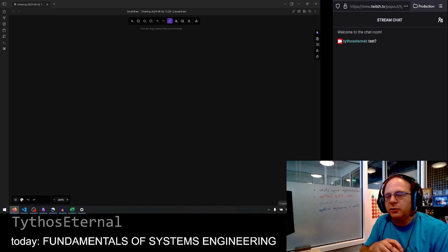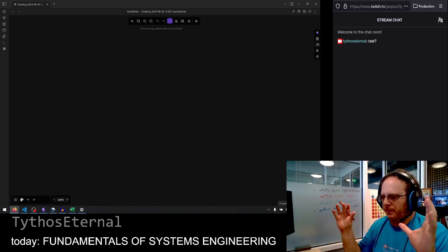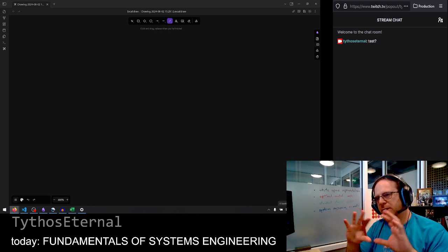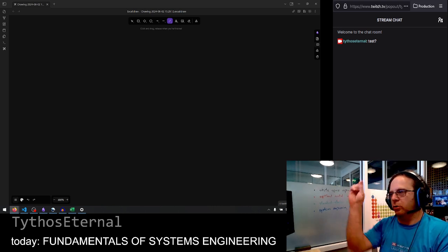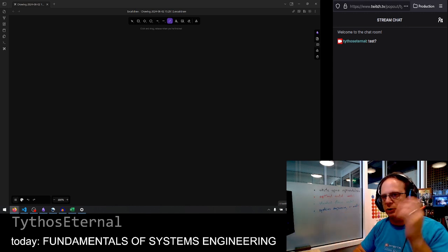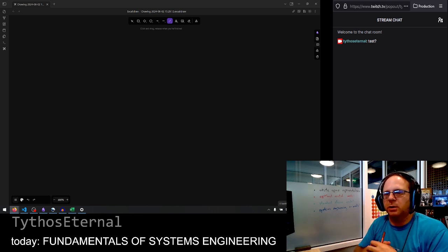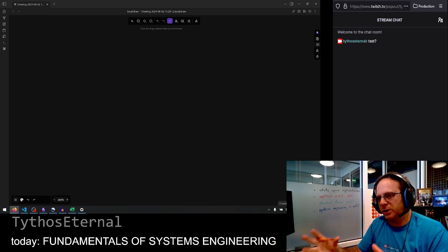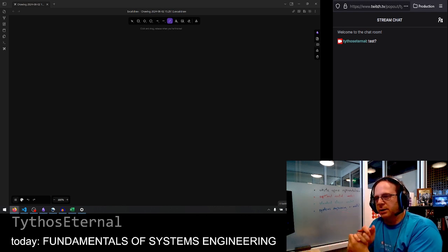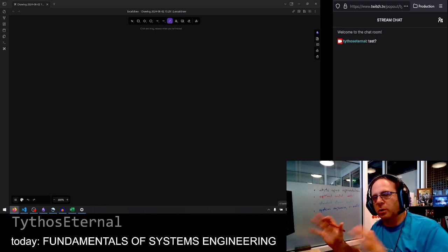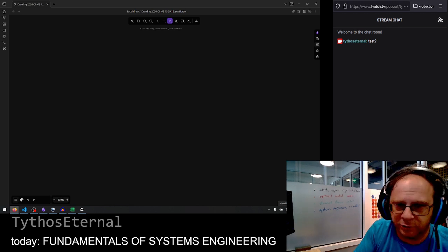something called state space. State space models are a very important concept in controls in particular because they help you model not just the behavior of a specific system, but how that behavior is controlled in order to get it to do something you want it to do: to get the robot arm to go over there, to get the rocket to stay on course, to get the bridge to stabilize after the car drives over it. There are many different situations under which you want to make sure the response of the system you're designing behaves in a very specific way, the way you want it to, in a way that's controlled and stays within your requirements and achieves the desired objectives. But this also goes into a lot of other different and interesting concepts, as we'll see in a moment.